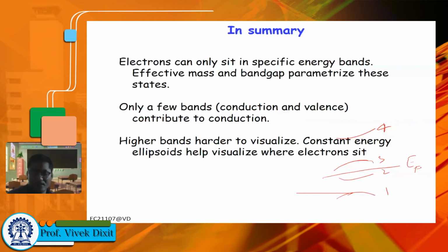Now we can recall also that in case of metals, the Fermi levels are inside the band, right? So they can also be represented like this. These are the bands. So in metals, the Fermi levels are inside the band. In semiconductors, the Fermi levels are between the 2 bands, right? So that means at 0 Kelvin, they are actually insulators.